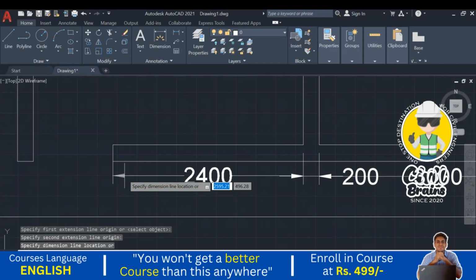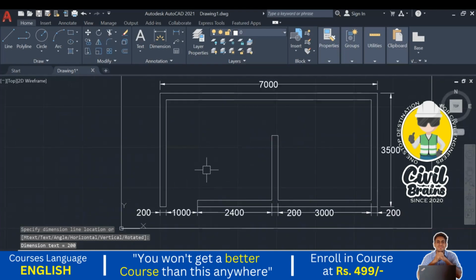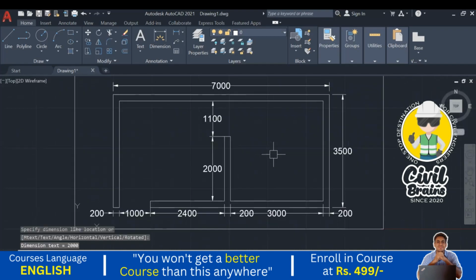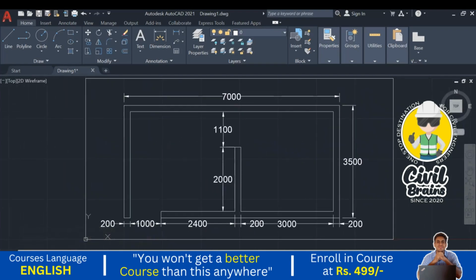If you want to take the same command, you just need to press the space bar. Once you press the space bar, you get this one. So I just check what this dimension is, 1100, and this one is 2000. So this is how we need to draw the plan. According to the exercise, only the plan they have asked. So we have drawn the plan over here with all the dimensions. This is how we need to do the plans.